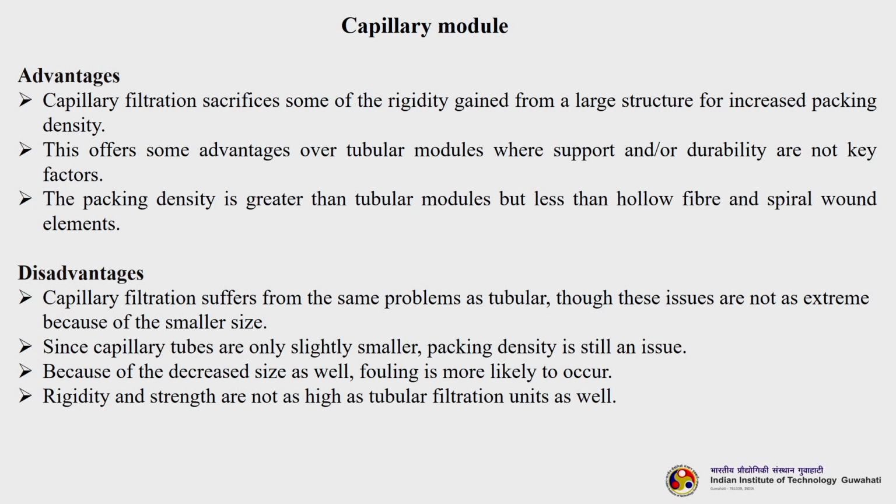So, the advantages are: capillary filtration sacrifices some of the rigidity gained from large structure for increased packing density. You do not have to go for a very large structure or very large system to achieve more packing density. Since they are self supporting, in a smaller space we can have more capillaries fused together to have a better packing density. So, this offers some advantages over tubular modules where support and durability are not key factors, and the packing density is greater than any other module.